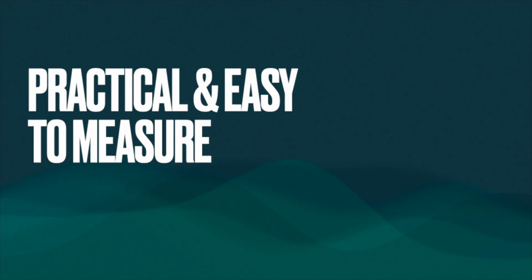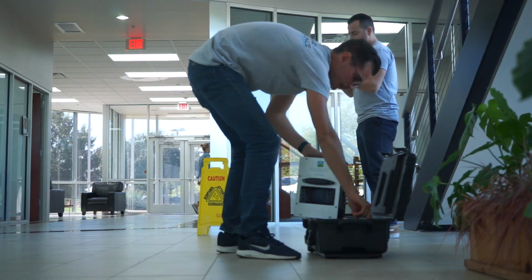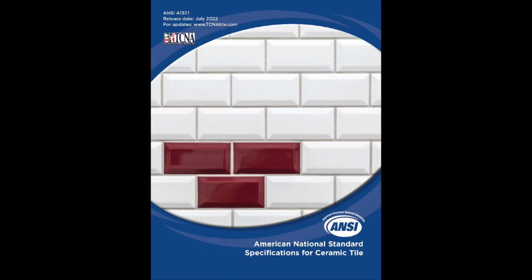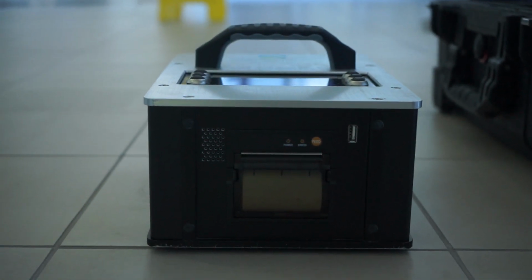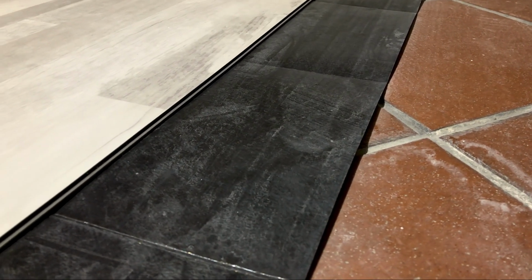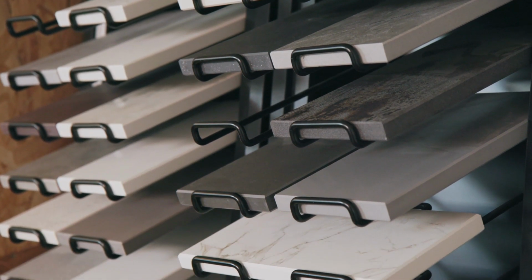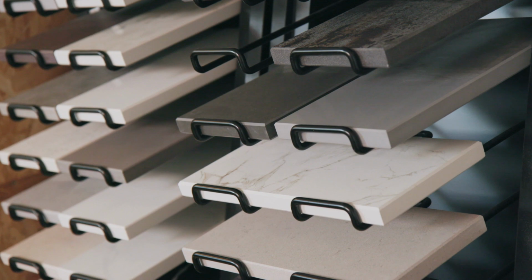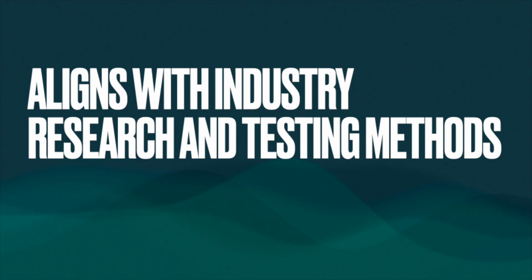DCOF is practical and easy to measure. DCOF is measured using portable standardized testing equipment like the BOT 3000E and standardized test methods like ANSI A137.1 or ANSI A326.3, making it practical and straightforward as a method for assessing slip resistance. DCOF is comparable and consistent. By using DCOF as a standard, it allows for consistent and comparable measurements across different surfaces and locations. This helps in establishing a baseline for slip resistance and enables meaningful comparisons between various flooring materials, coating, or surface treatments. And DCOF aligns with industry research and testing methods.